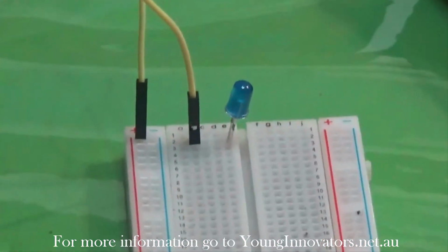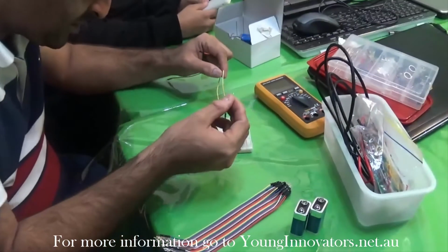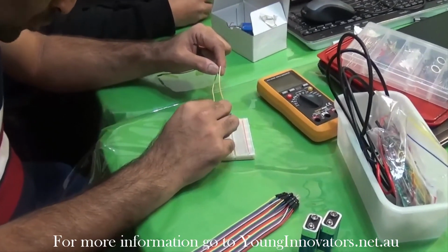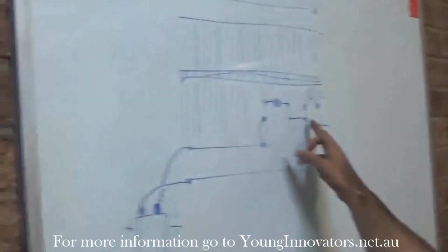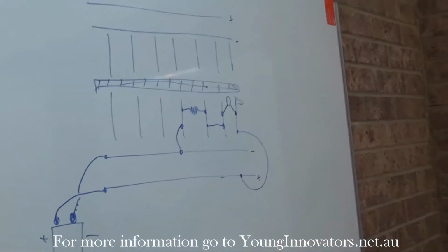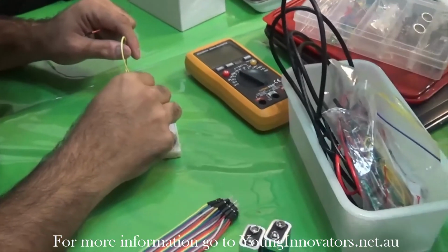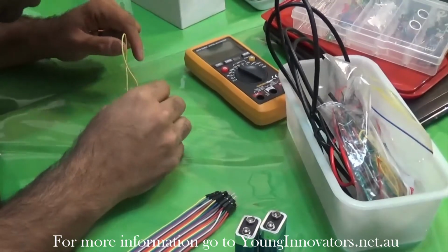The resistor goes exactly the same way as the LED, right? But the resistor has to connect to the negative of the LED, so it has to be in the same row to be connected. So we have to connect it here. You have to be a bit careful how you connect this.